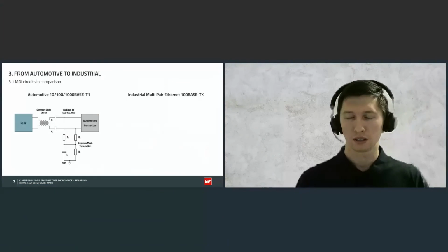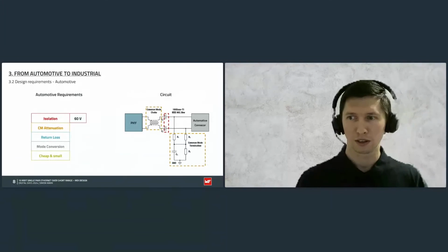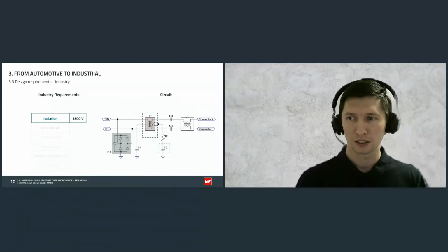That's a good question. You can open the PDF you get from Markus, and inside, on page 27, I mentioned that there are 3 different capacitor values, from 100 nanofarad with a droop of 13%, up to 470 nanofarad with a droop of 7.8%.